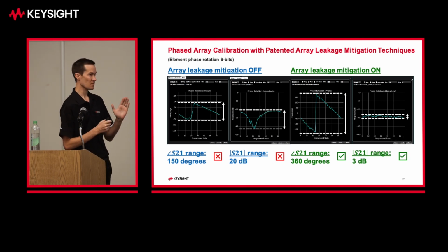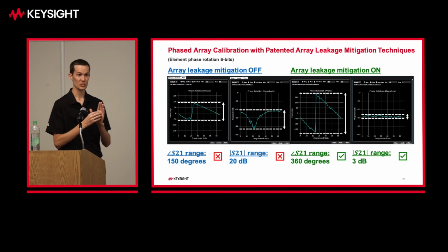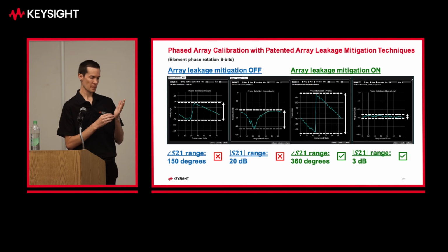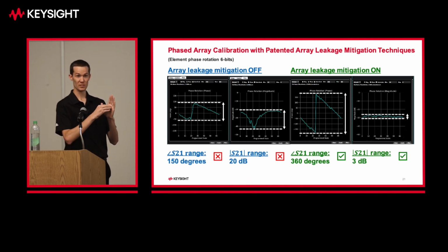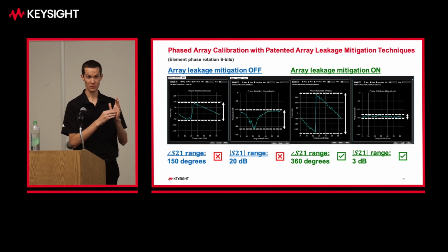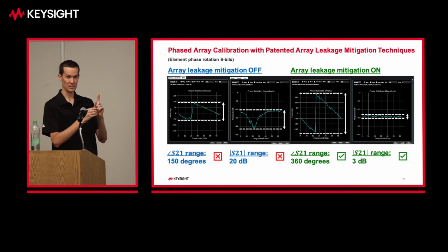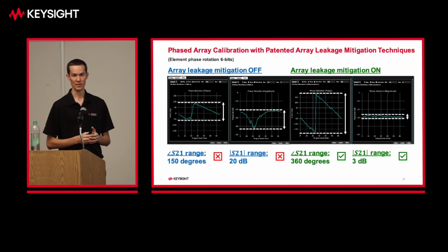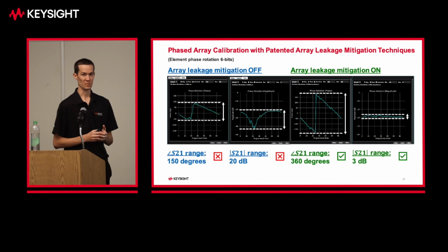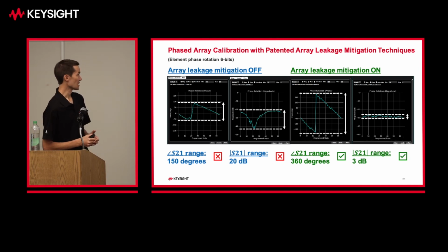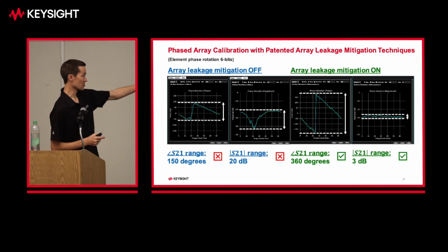So what we do is we have all the ICs on, and we can measure the individual element channels by removing the leakage effect, which is applying maximum attenuation to the other elements so that we can try to isolate the one element under test, but we still have some measured power that corrupts the measurement. That's kind of this residual power that's being radiated from the other elements. So we have some techniques we've developed to correct for that effect, and that point is illustrated here.